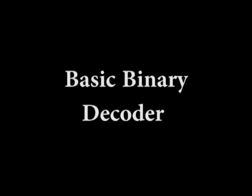Here we shall be discussing the basic principles of several decoders, and these basic principles can be extended to other types of decoders. The basic binary decoder. Suppose you need to determine when a binary 1001 occurs on the input of a digital circuit. In such a situation, an AND gate can be used as a basic decoding element because it produces a high output only when all of its inputs are high. Therefore, you must make sure that all the inputs to the AND gate are high when the binary number 1001 occurs, and this can be done by inverting the two middle bits as shown in the figure.